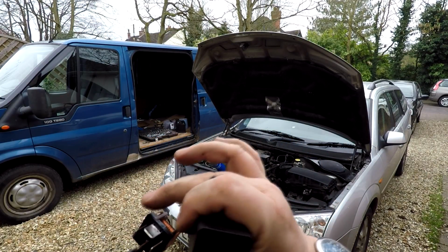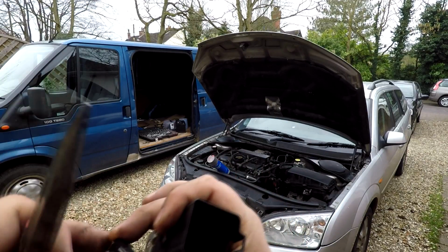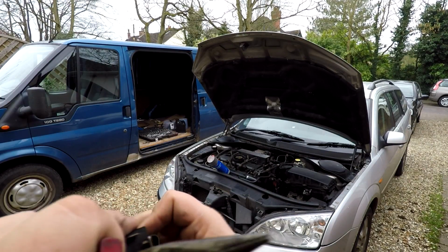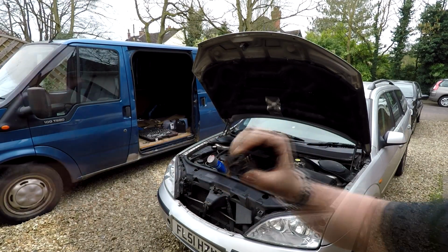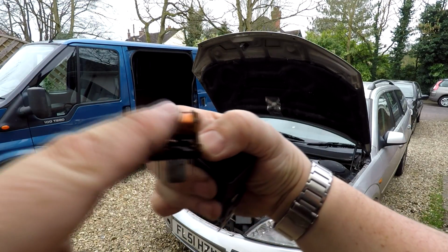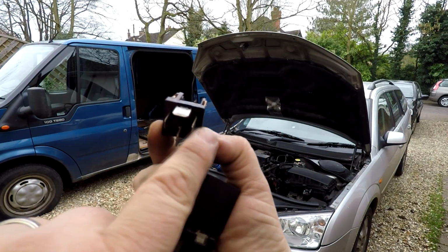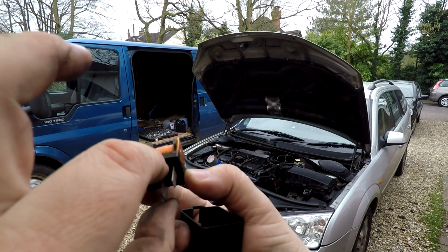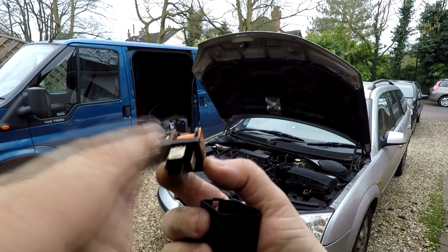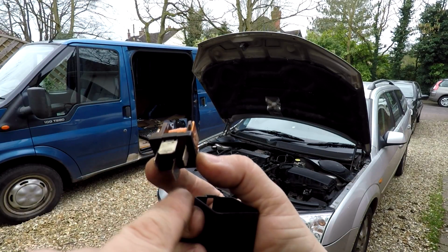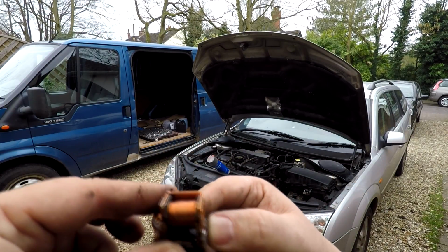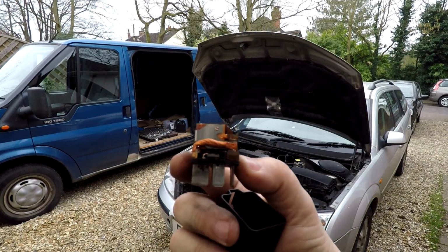Now the only thing I'm telling you to note here is that pin number 5 was the bit nearest that little cutout there. So when it goes back in, pin number 5. I'm only doing this because I don't have a replacement to check it with, and the replacements are quite dear. There's the coil I spoke of, and that connects down to these 2 smaller terminals there, as you can see. So if you apply voltage to that, it should close a set of contacts, which will then allow current to flow this way. And this is the controlling cable that will go to your fuel pump and provide its feed. Now don't forget, you can see by the size of the cable there that quite a lot of current probably flows in that, because it's quite a big cable.